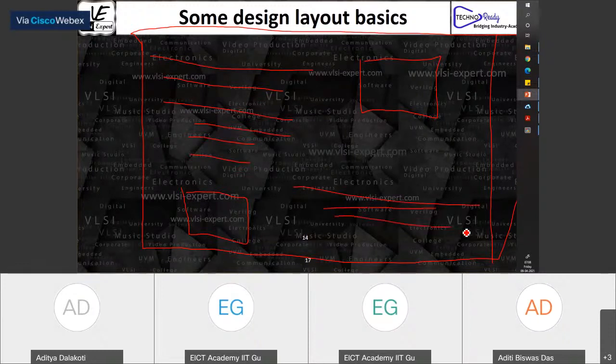Now, in particular, closer to your macros, because these macros have a lot of pins, there are a lot of routing constraints. You have to route a lot of signals here in a very small area. So the exact analysis I described for the standard cell routing layers, the tool does for the macros as well. It tries to figure out, okay, I have to route, say, 100 signals to this macro.